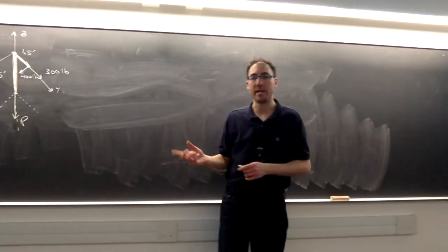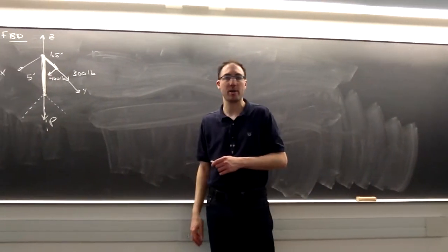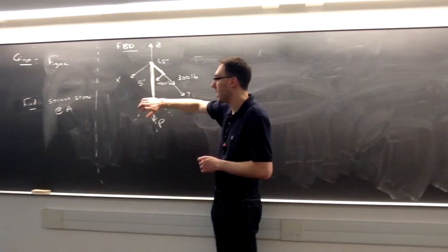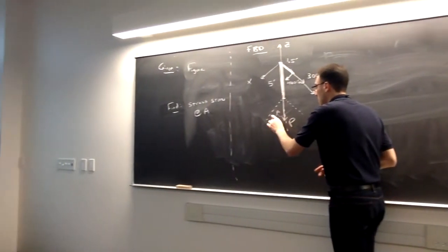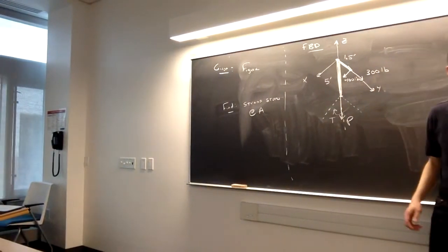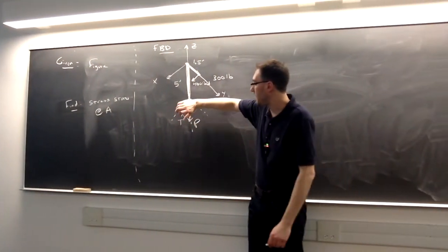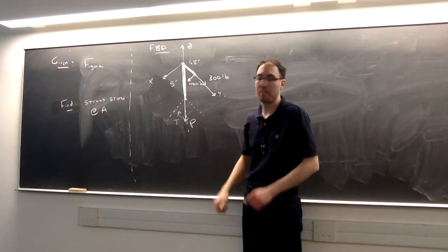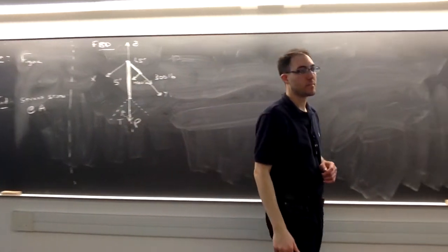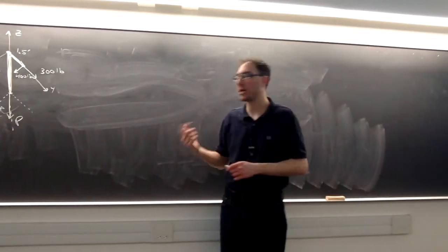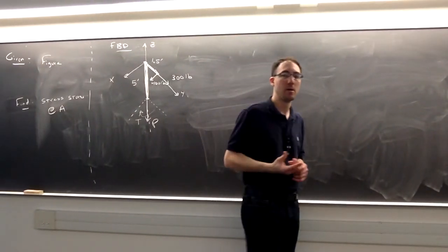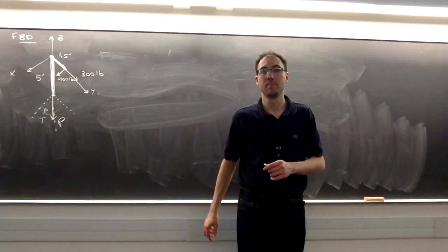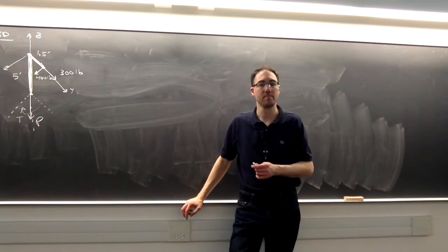Then our assumed direction of torsion is determined by going positive around that P direction. So we'll have that internal torsion T that's positive using the right-hand rule around P. Again, the direction of P and the direction of T are determined by the outward normal from our object, or from the cut surface.